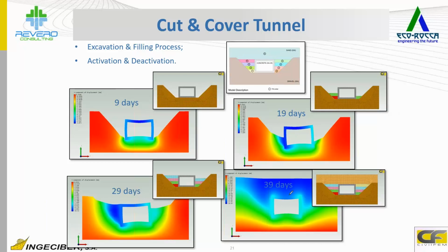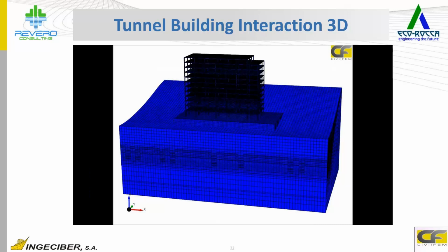We have the capability of simulating the process in time, and you can see here that at different days we had different stresses and displacements within the ground. We can do later an analysis of the structural status within the elements of the tunnel.